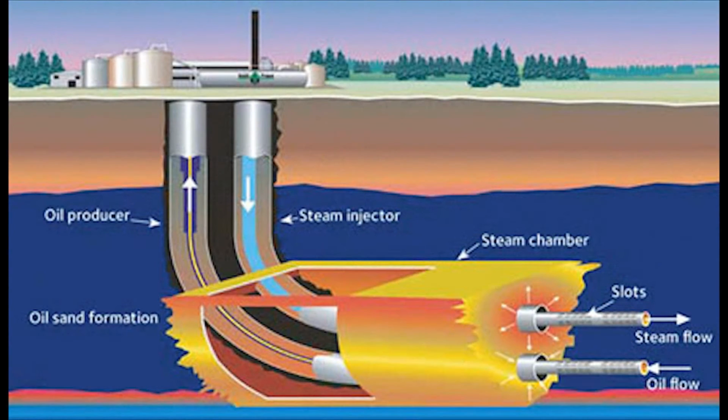Alright, now we're talking about the challenges in horizontal well testing. The first one is the heavy oil environment. Why? Because the ESP, electrical submersible pump, needs to be integrated with the DST, drill stem tests. Fluid handling with conventional equipment is very complex, due to the pressure drop and extra heat requirements.